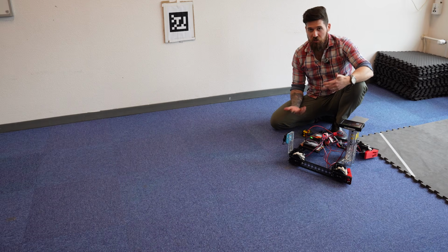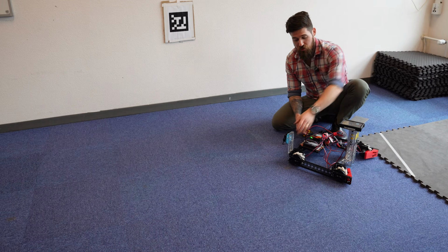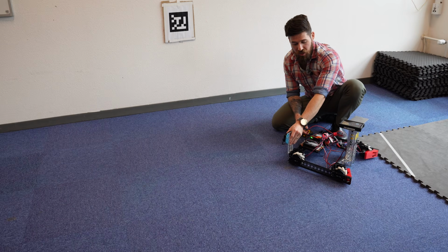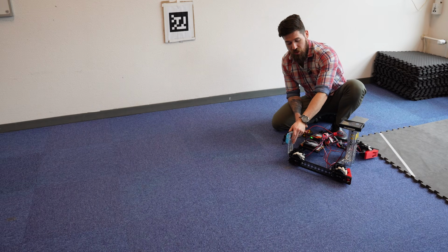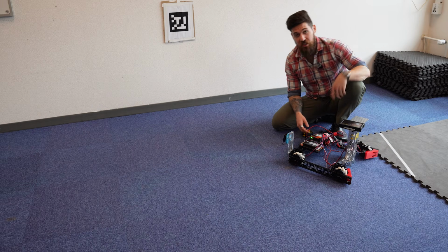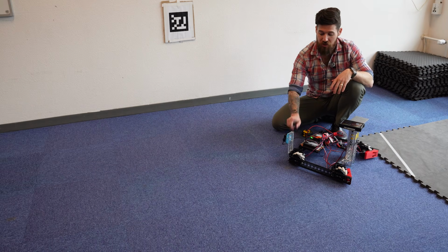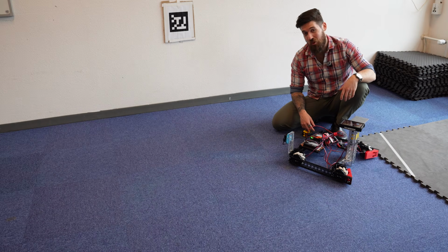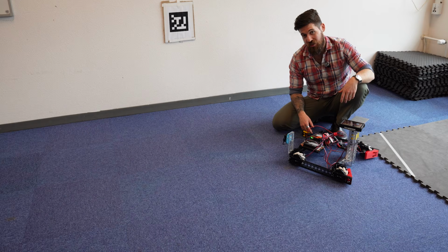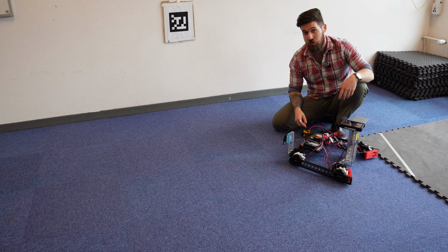Another thing that commonly goes wrong here is that what you think may be in CAD may be different in real life. So for instance, if you look at this angle here, I'm capable of changing it by almost 2 or 3 degrees, which is pretty significant. So if you are able to shake and rotate your Limelight or bend the aluminum mount that it is on, that is also going to significantly change your accuracy. So make sure you have a very robust, stable mount, unlike the one that I'm setting a poor example with of not having a robust angle. Because even though in CAD it might show up one way, the reality might be a little different.